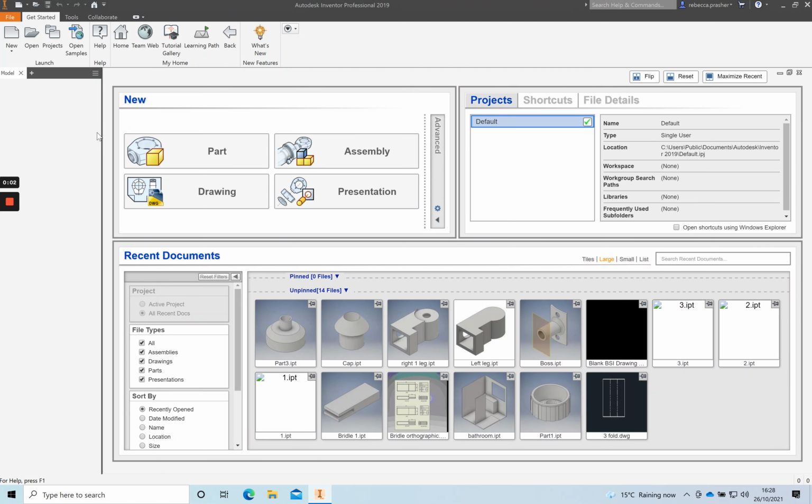This video is the Higher Graphic Communication LAMP project, and it is part 4, which is the shade. Now we can see in the drawing of the shade that we have a bigger circle that tapers into a smaller circle at the top. So we are going to use the loft command because the profile changes shape as it moves along the object.